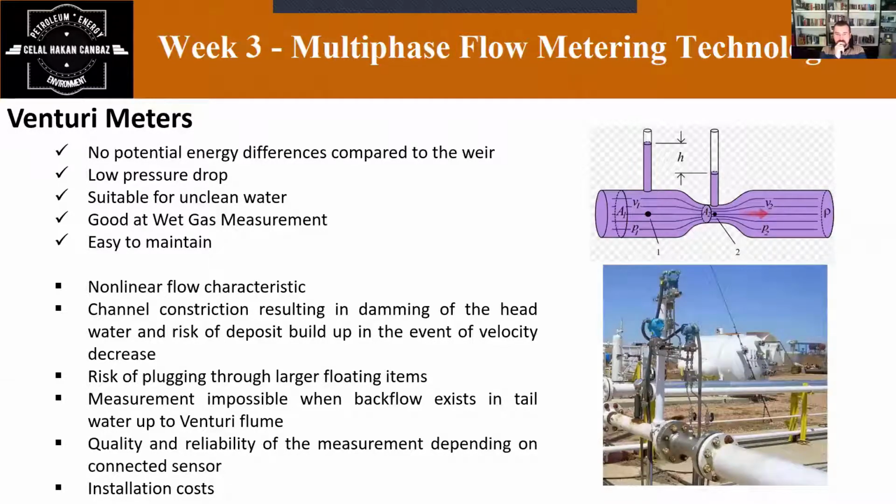Without knowing it, you want to continue your flow, but your tanks are full, so it's making a backflow. Because of that, you directly see very big fluctuations in your data, which gives a very high error percentage at that time. You cannot get any production results. So it's one of the main issues of this Venturi meter.